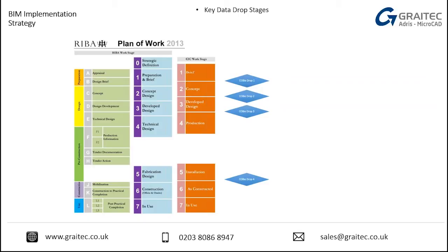In reality, you probably wouldn't trust a carpet fitter to fill in that spreadsheet because it's a single spreadsheet and then send it back. He'll probably just provide that information to the BIM coordinator, the BIM manager, whoever the lead is, and they will then propagate this spreadsheet. But this will be a spreadsheet that is then handed over to the FM people afterwards. A lot of the FM software is already now geared up to read and understand the COBie spreadsheet data format.